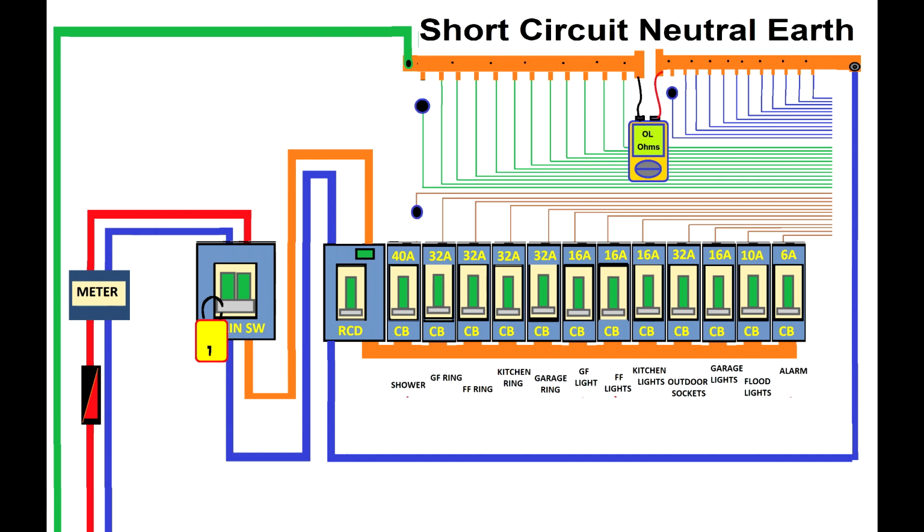After you disconnect the faulty circuit, you will measure between the neutral and earth bus bar, and then you also disconnect the live of the circuit. Then you will prepare to reinstate the rest of the circuits, and later on you can start working on this faulty circuit.